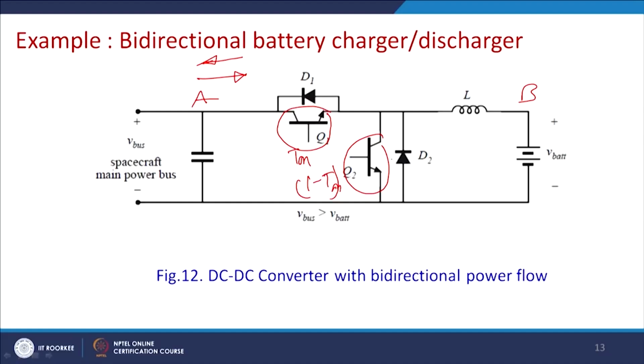So, it will be shorting, so actually there will be a huge voltage built up across it, and ultimately the diode will be forward biased above VA, and ultimately power will flow back to the main bus. So, to realize a bidirectional DC to DC converter, this SPST switch will be converted to the SPDT switch, and so this can be realized.